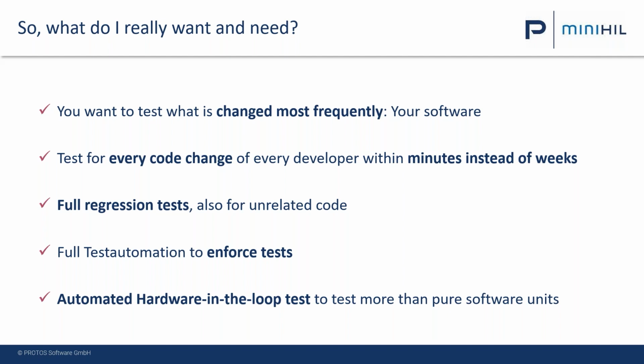If you only have software units, then it's better to use a unit test tool, much cheaper, much faster, much less effort. But if you have hardware attached to your system, so a microcontroller and an ECU, eventually you will need a hardware in the loop test.